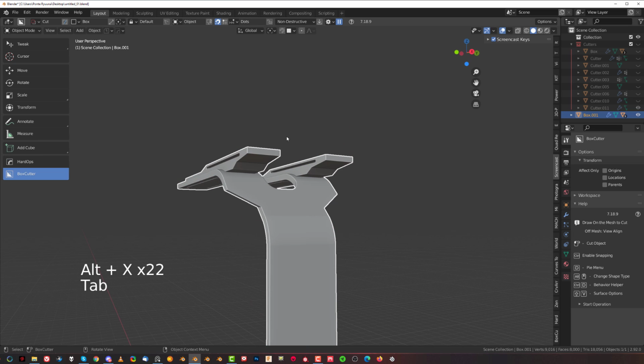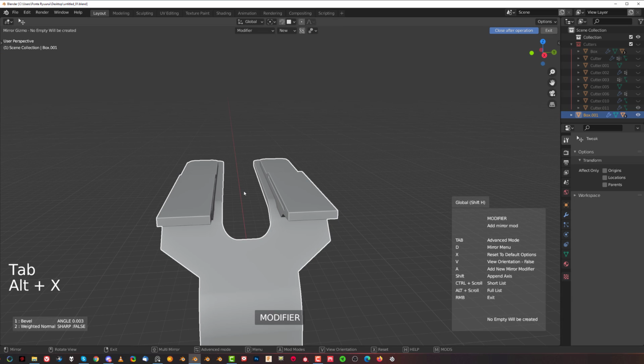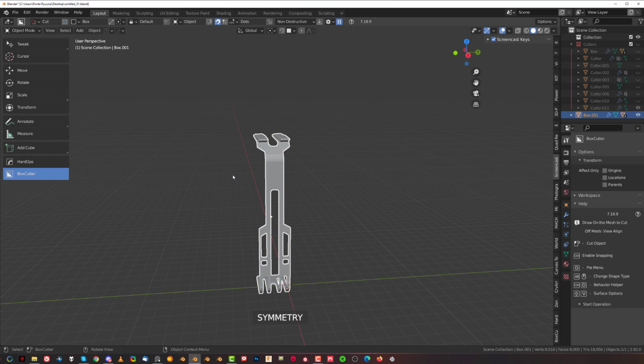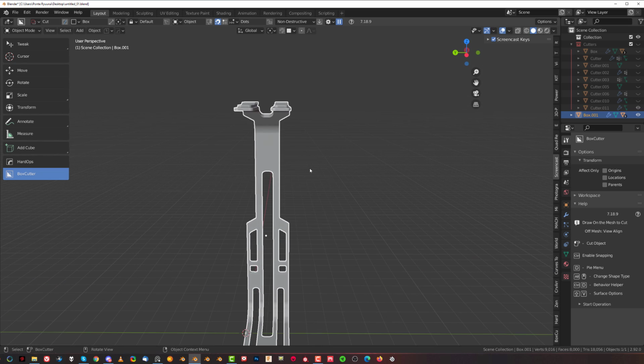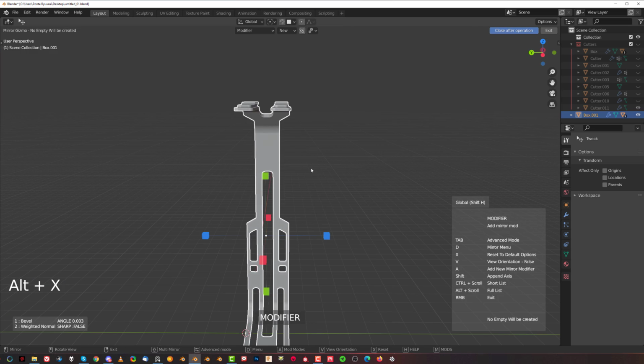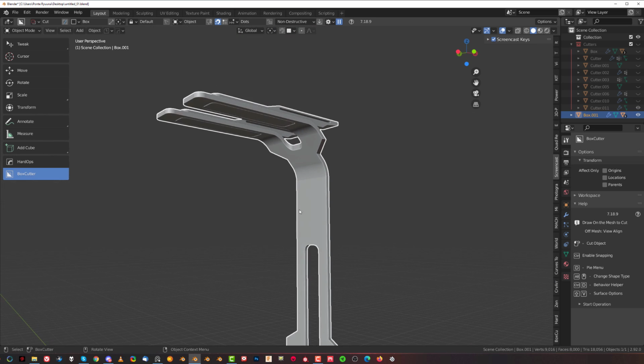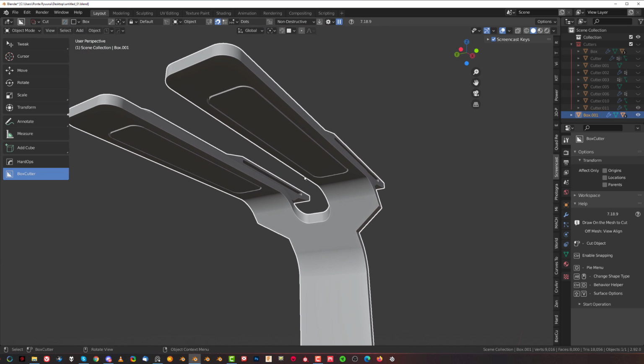If you don't have Mesh Machine, what you can do is go to Solid View, Alt X with Hard Ops, press D, Symmetry, and symmetrize it, and then make sure that you reset the mirror next time. So Alt X and press X to reset the mirror from symmetry to modifier. Okay, so that's how it works. But Mesh Machine is fantastic for symmetrizing very quickly.